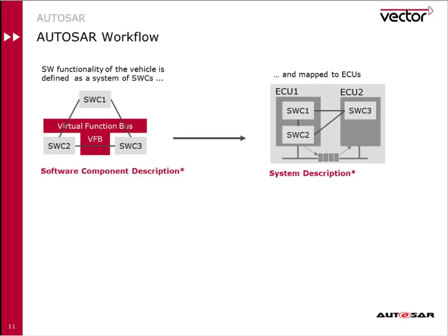And in this example, we can add software component 2, the tyre pressure monitoring system, into the already existing ABS ECU. And of course, the additional message that flashes the TPMS light on the dashboard also has to be supported through the communication parameters. But again, in this instance, we haven't really thought about whether it is CAN or FlexRay. That's not typically quite so important at this point.